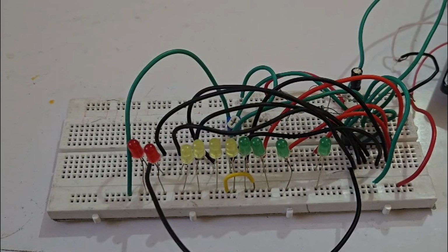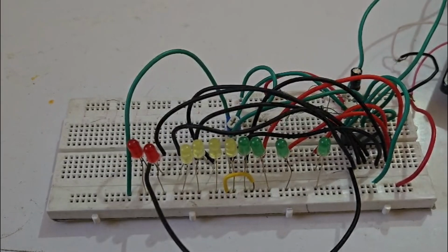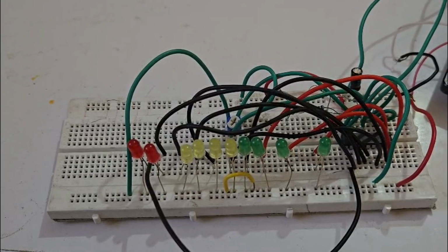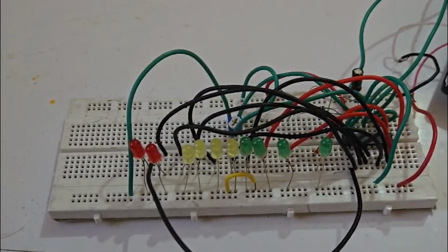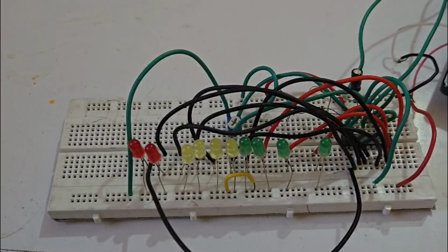In this circuit, we have used the IC LM3915, which is an LED indication IC consisting of 10 comparators. Before, we saw why space management is required in advanced mixed signal ICs. This solves that problem, as this IC consists of 10 comparator circuits with a 10-step voltage divider circuit, which makes a different reference voltage for each comparator in the IC.